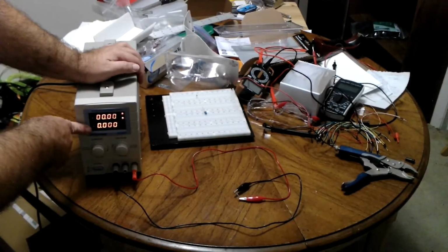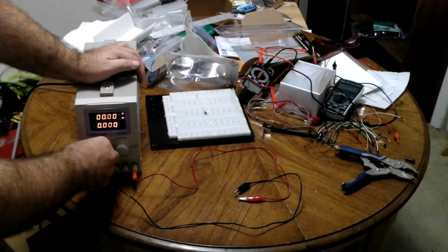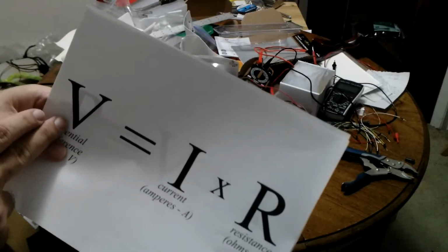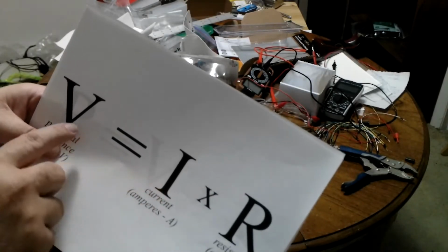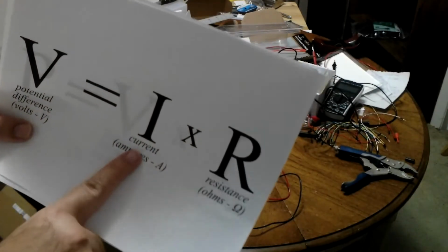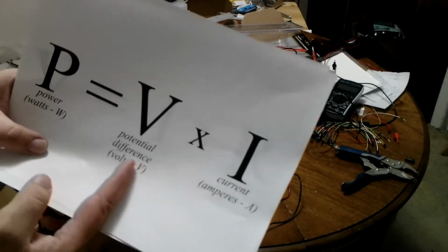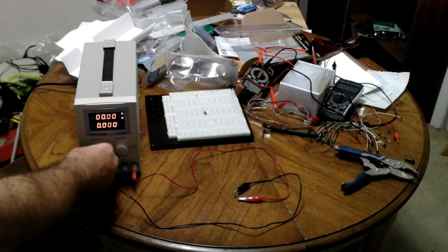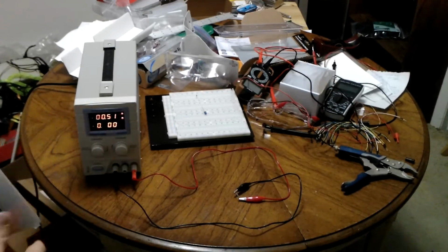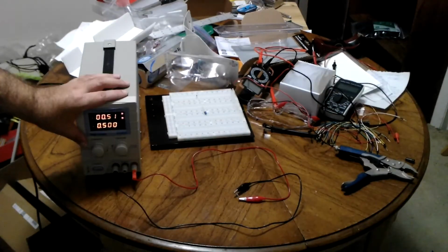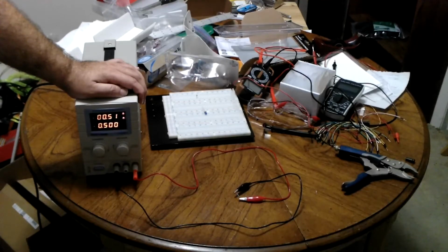If I set this current limit to 1 amp, I should get 1 volt. So let's set it to 0.5 actually. 1 ohm, 1 amp, 1 volt. If I want to make this 0.25, I'm going to set the current to 0.5 amps, which will be 0.5 volts. 0.5 times 0.5 is 0.25. So half an amp should give me half a volt. So 1/4 of a watt is now going across this resistor, right here. Since I don't have a meter that can measure the actual power to demonstrate the equations, we'll instead do a practical demonstration.